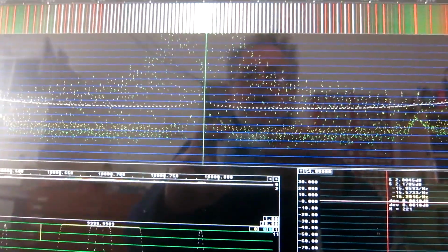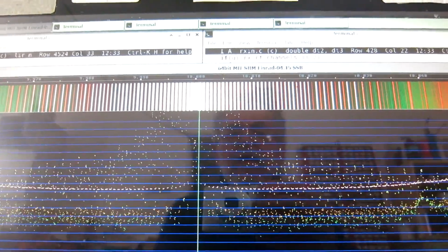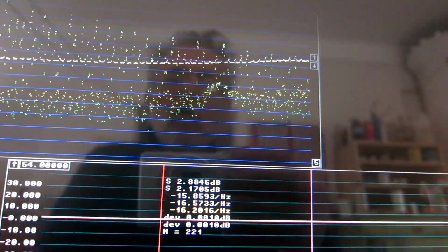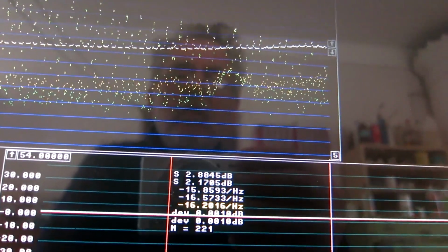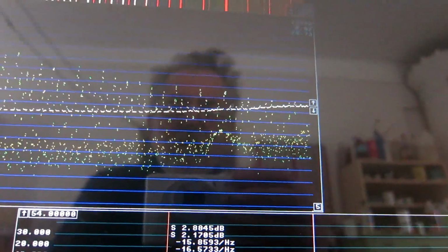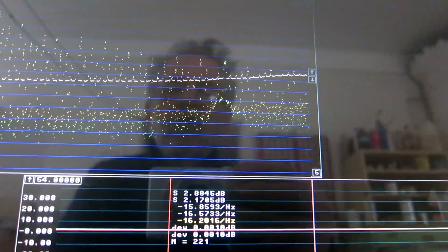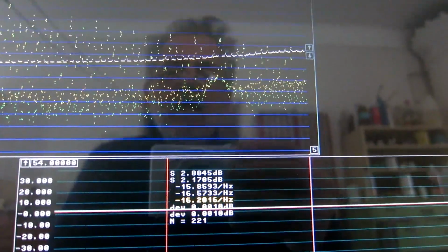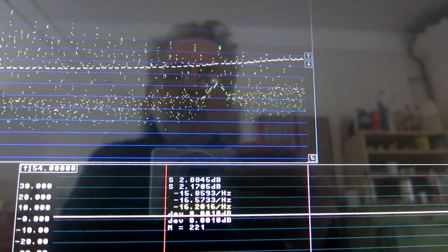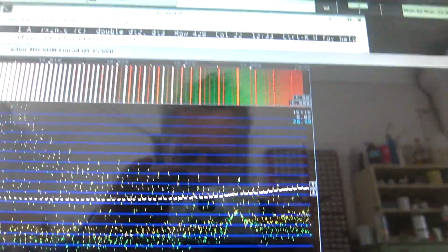I have reconnected the mixers and clicked on the carrier, the main signal, to read the power, which is plus 2.5 dB on the average. I forgot to do this calibration before I did the noise measurement, but I can equally well do it afterwards. There is a 2.5 dB error.